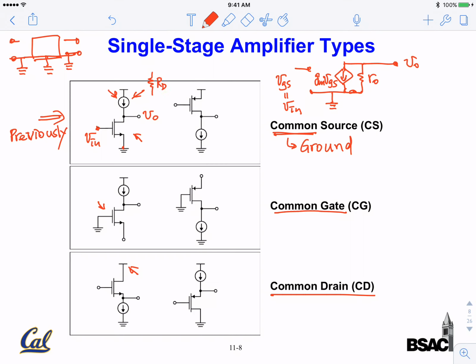A current source is a better biasing scheme. So later we will have a lecture comparing different types of bias options. In the lab you're doing now, you simply use a resistor to bias it. And later when we go to the biasing lecture, you will find that actually a transistor is the best bias. We also mentioned whenever you can use a transistor, it's actually better than a resistor. It is smaller, more compact, and usually gives you better characteristics.